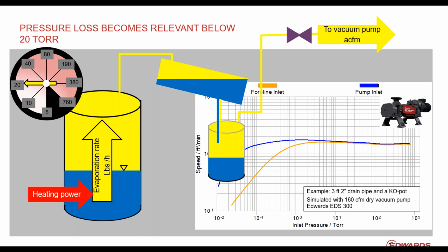torr vacuum. But the drain pipe is typically, what, 2-inch? Because it's designed to drain liquid. So your vacuum pump basically pulls vacuum into the reactor through that drain pipe. So you have a two-phase system. So you drain the condenser and you basically pull vacuum through it. Again, doable, but it's a major restriction if you want to get to better vacuum.